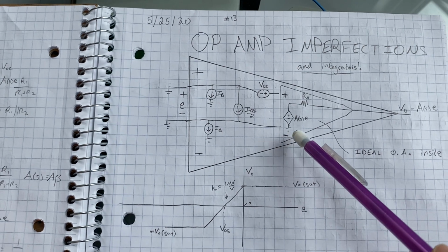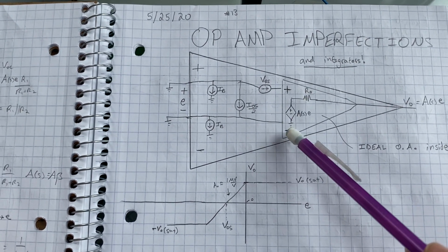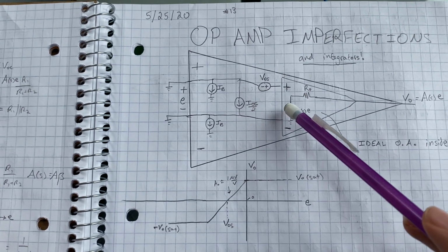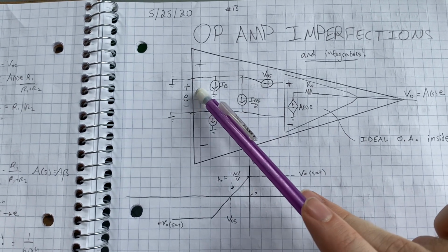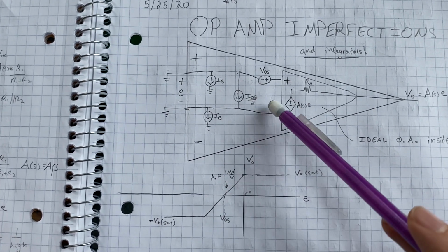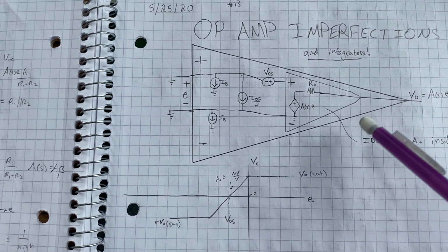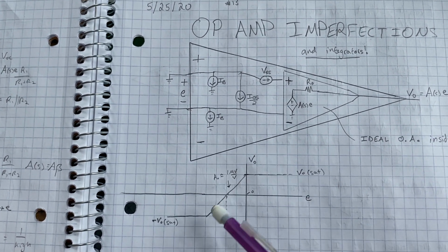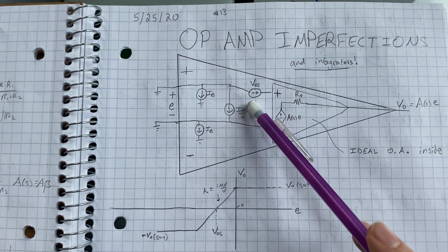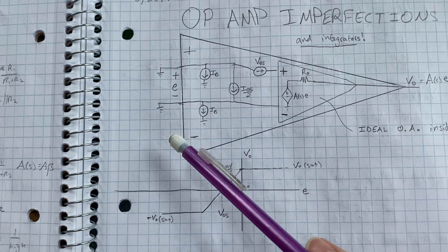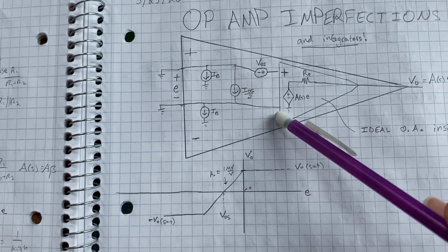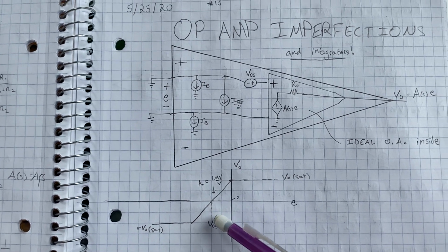And if we know that the output is some large amplification times the difference between the voltage of the pins, it makes sense if we define that error voltage between the pins here, because then the offset voltage, when we take our true output versus here, affects our transfer function. So we can see here, because of the presence of this offset voltage, our error voltage needs to be in the opposite polarity for this to actually have 0 volts across it and us to get the 0 output.